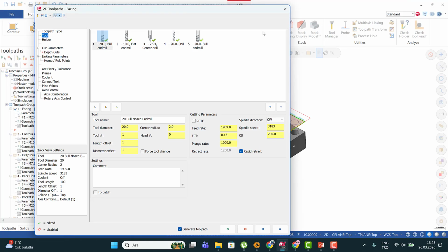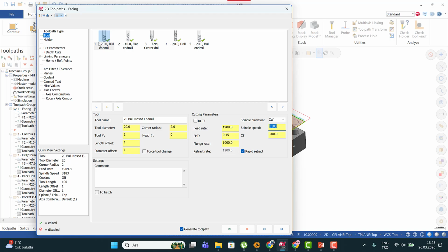This is the Mastercam perspective: you just focus on your tool catalogs, decide your cutting speed and your feed rate per tooth values, and then the feed rate and the spindle speed are calculated. Of course, you need to be careful about your tool diameter. Tool diameter is also a quite important parameter.